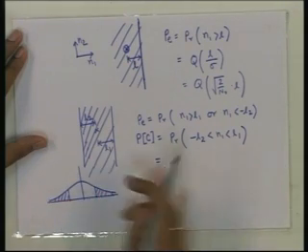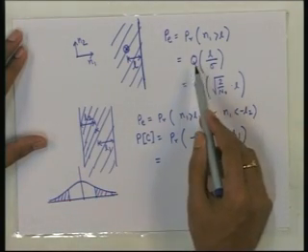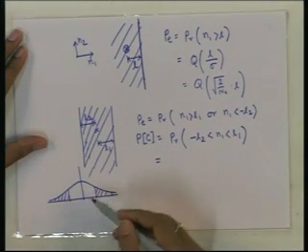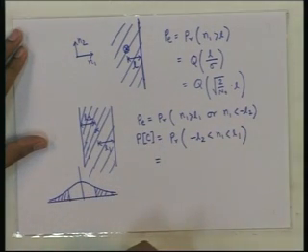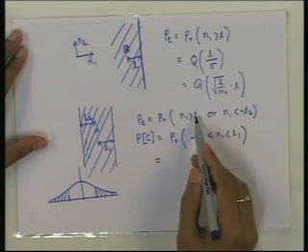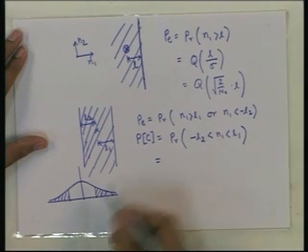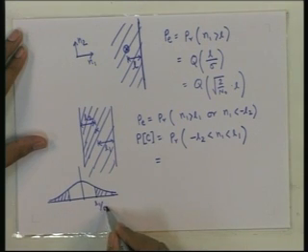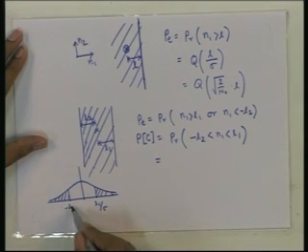The Q function is the area of the Gaussian PDF with unit variance, whereas the noise may not have unit variance to start with. So, we need to normalize this point. We have seen these details in the last class. So, this will be L1 by sigma, and this will be minus L2 by sigma.